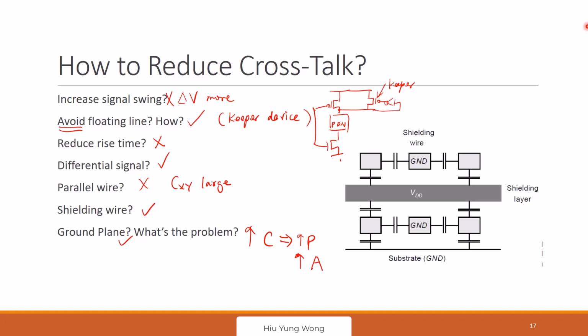You worry about all this matching, and the jitter and skew might not be a big problem because you're not doing register. You see what I mean? For analog circuits, when you use this clock, jitter may have the noise, but maybe I'm wrong, it's less important in terms of jitter and skew. But if you put it between registers, then it becomes important.